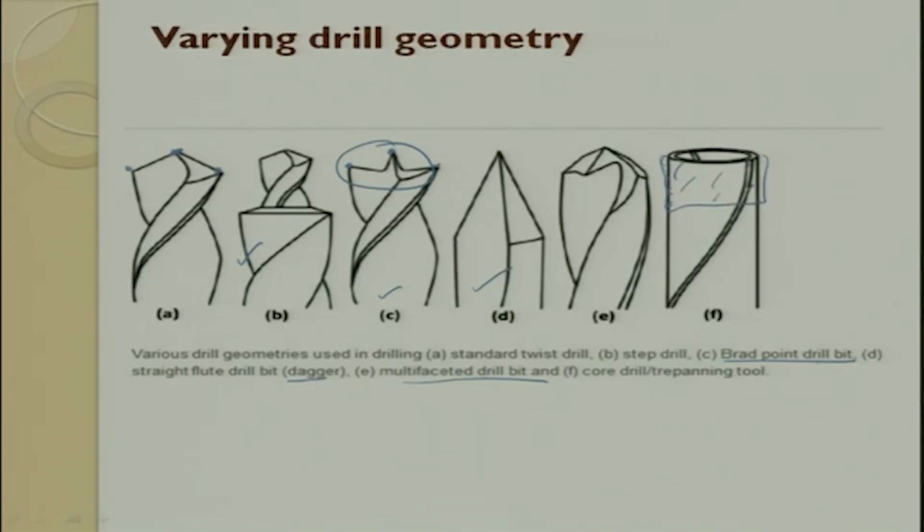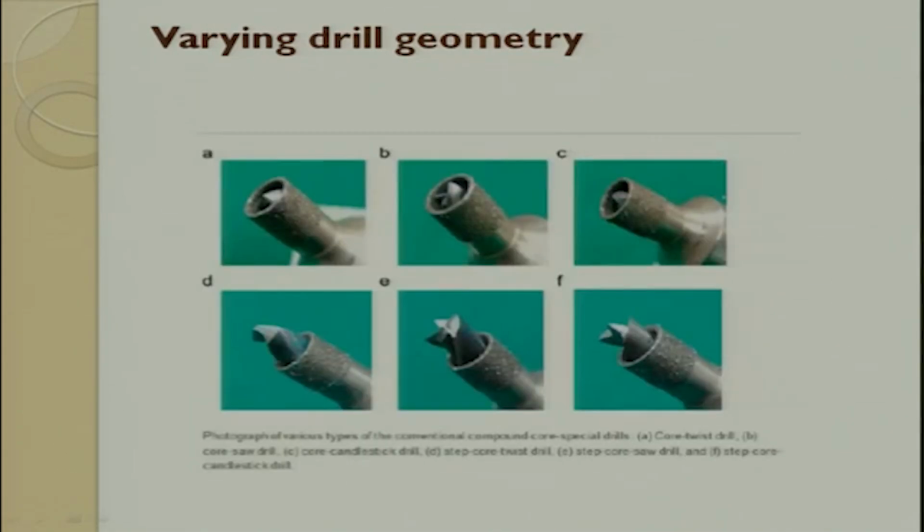This operation is called a trepanning operation. You have a core, a cylinder, and the cutting portion of the cylinder is at the top. We try to disperse diamond abrasive particles in it. Because the chip is not continuous, you get a powdery chip. This geometry is also accepted for drilling of holes. So, this is the figure I was talking to you about.